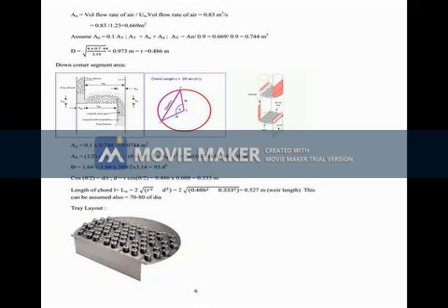So 0.02 into 0.064, which is 0.00128. Then this is capital Y1, small y1 will be slightly less than that, 0.00127. Now Gs is the amount of pure air. It is Gn plus 1; if you know yn plus 1, that can be determined. It is coming around 0.03196.